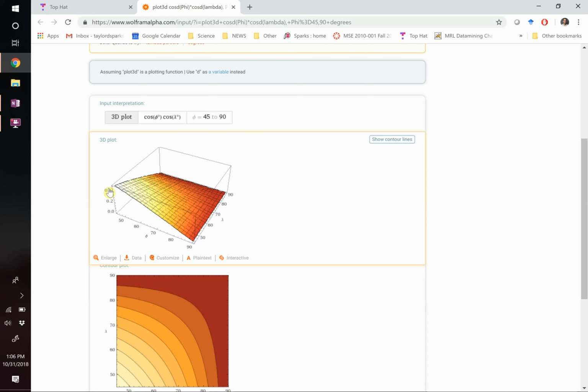So if you had a single crystal and you could choose the direction in which you're going to load it, you'd choose the direction such that your slip plane normal and your slip direction are orthogonal to one another. They have to be, right? Because the plane is right here, the slip is happening in that plane, and the normal is perpendicular to it. So they have to be 90-degree angles already. If you then load it so it's 45 degrees between the two of those, that's the highest strength that you'll get out of a single crystal. It's just mathematically what comes out of that equation. Okay?